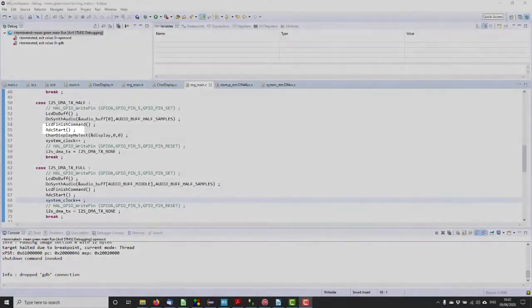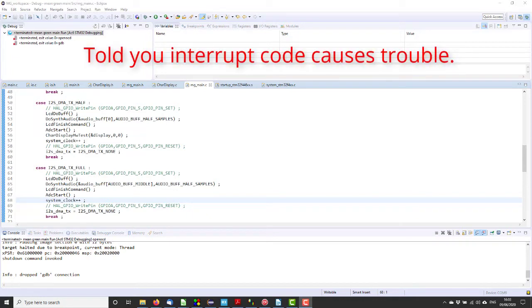However, I did discover that the LCD control lines use port B, and the multiplexing lines are also on port B. The multiplexing lines are set in interrupt code, and the LCD control lines are set in non-interrupt code.